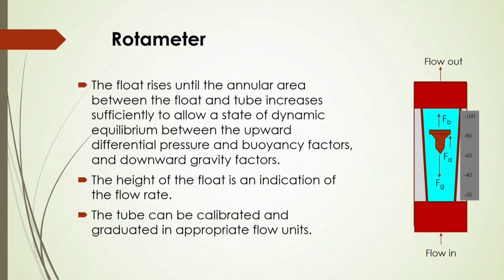If you change the known flow rate of fluid, you get the respective scale reading of the float where it is in equilibrium.